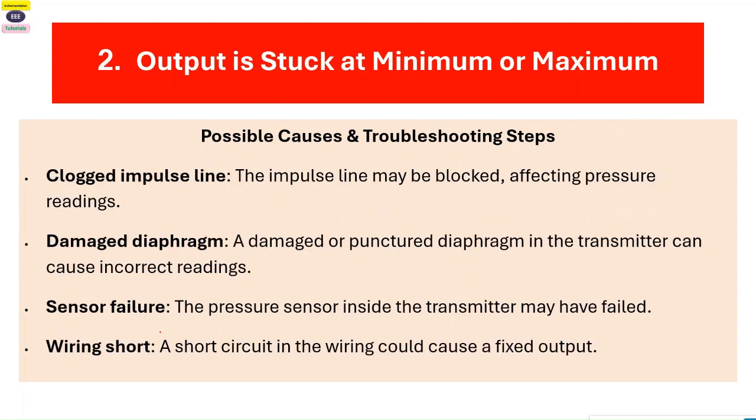Now the second problem is your output is stuck at minimum or maximum. The first reason may be a clogged impulse line. You have to check your impulse line, as it may be clogged with some process material.